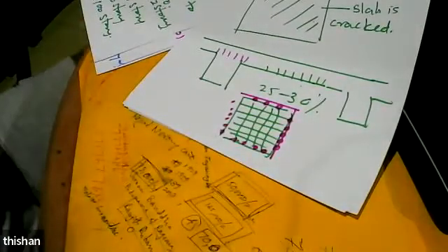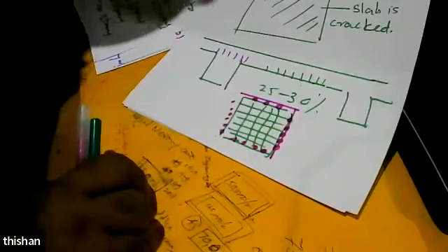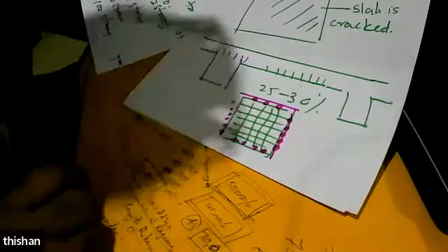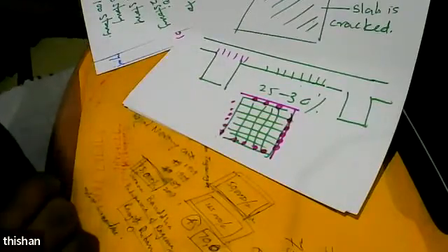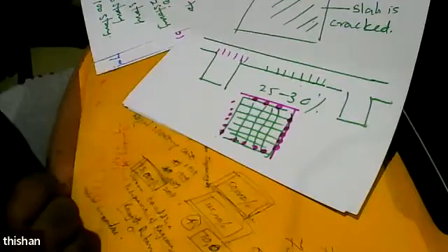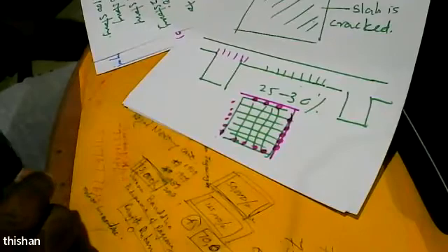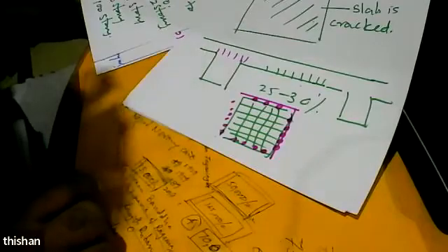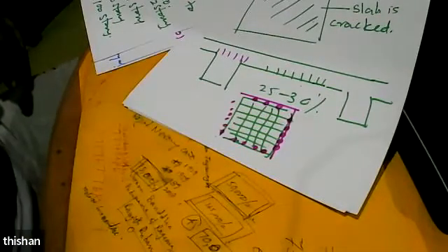So you model the beam, the slab elements, and you ensure that there's connectivity to the beams. Now you are going to get a massive stiffness unless you say the slab elements have only 25 to 30% of the stiffness of the actual slab. Then you will be okay. So you set modifiers, reduce the stiffness of the slab by reducing the second moment of area of the slab. So we say set modifier, where the slab is represented is 0.3. 0.3 stiffness is reduced in both directions.